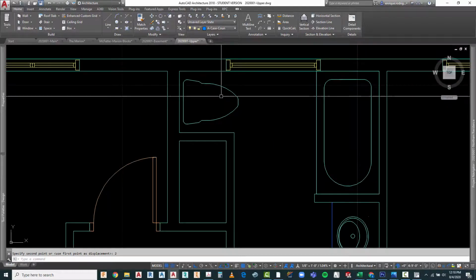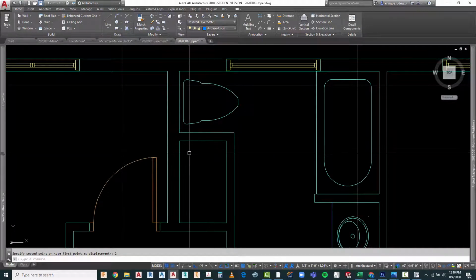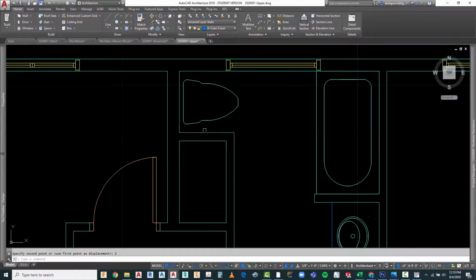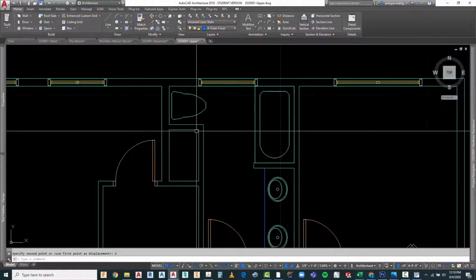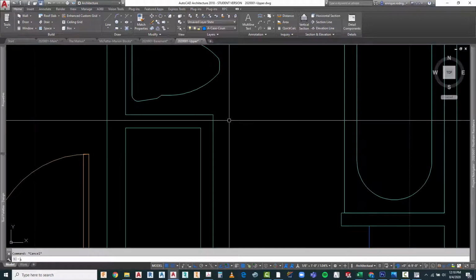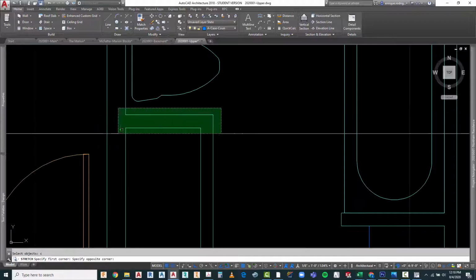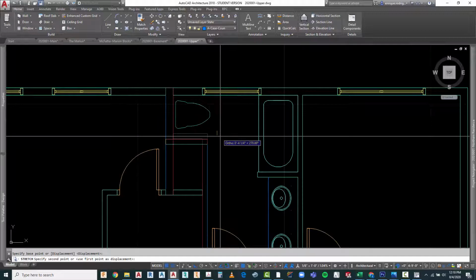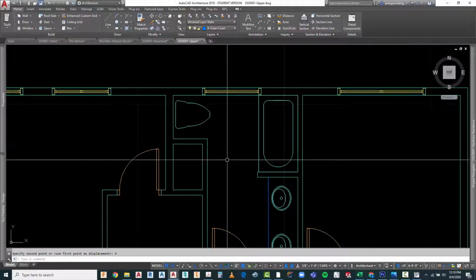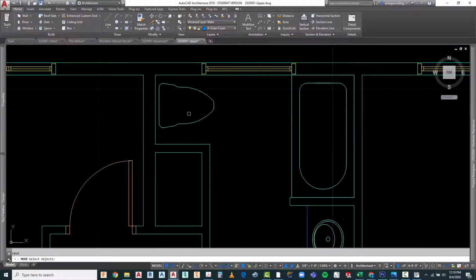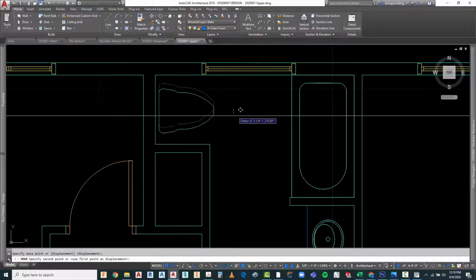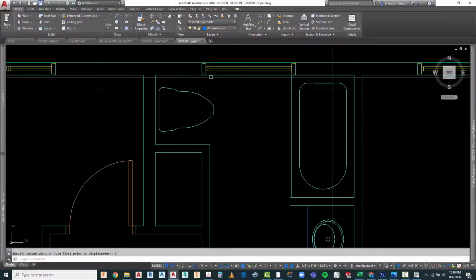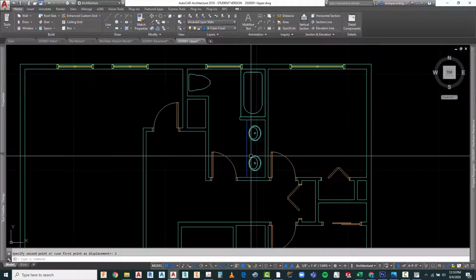Now, if you think that this is a little bit tight in there, because we only have one of these flues going out now, I'm going to go ahead and make this a little bit bigger so we have a little bit more elbow room, and pull it out 4 more inches. And I'm going to recenter that by moving this down 2 inches. And that looks like I got a little bit more room to work with.